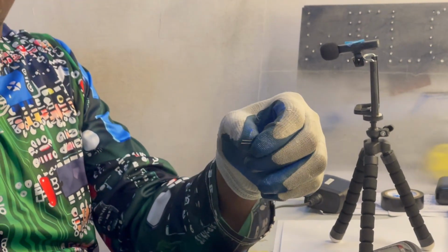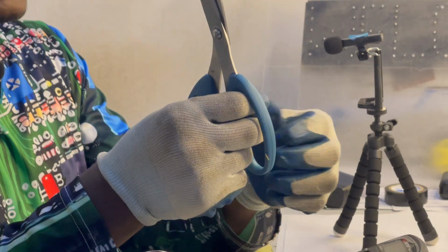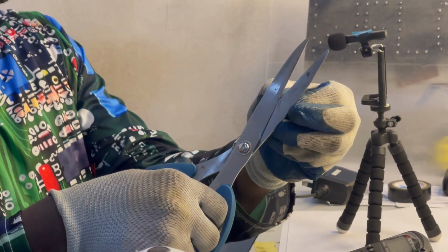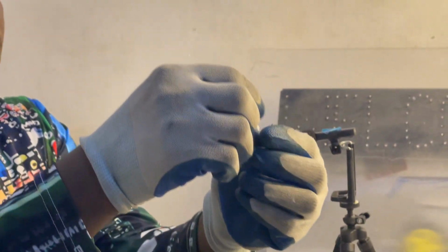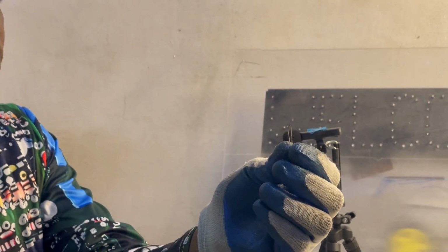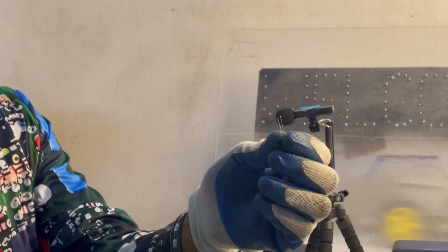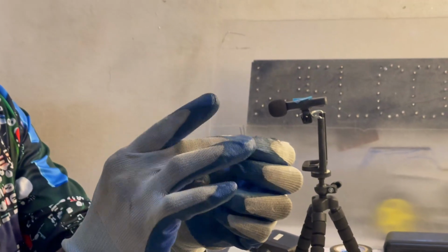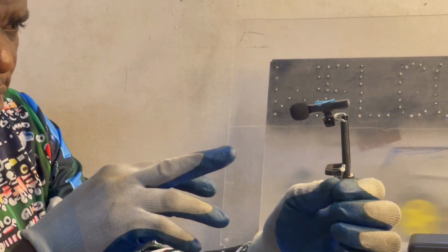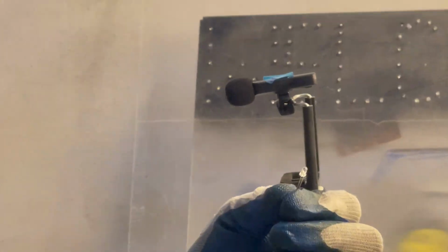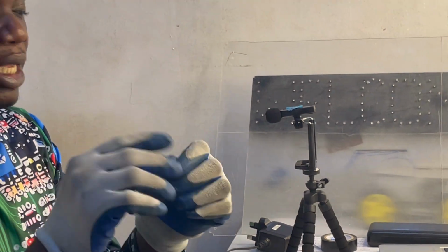But in a case where you are taking it from another system where it's been used for longer and it's not a new one, unfortunately the two terminals are equal in height. So what can you do now to differentiate? You can't use the longer or shorter terminal to identify it right now. What you do is look inside the head. You see a smaller head and a bigger one inside. The smaller one is the anode, while the bigger one is the cathode.